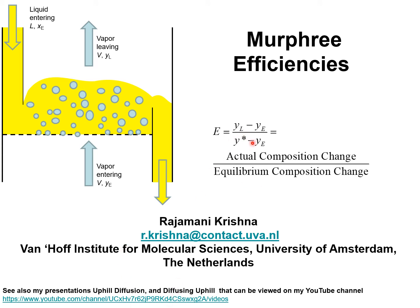To gain insights into the component Murphree efficiencies, we need to adopt a more rigorous model for interphase mass transfer than afforded by the Fick's law of diffusion that is commonly used. And in this context, I refer to my presentations on uphill diffusion and diffusing uphill that are available on my YouTube channel.